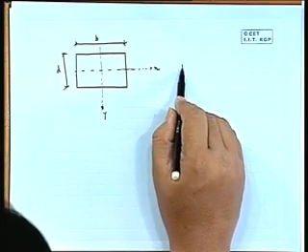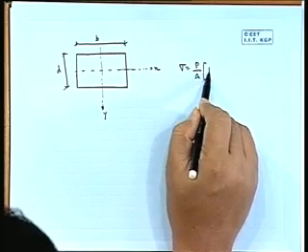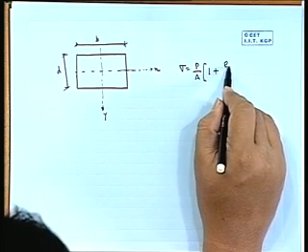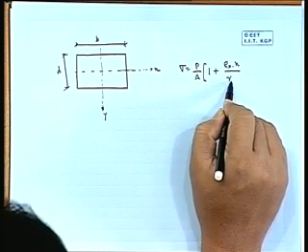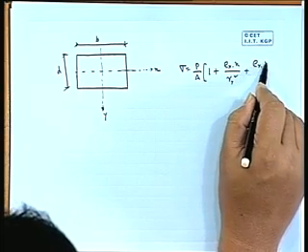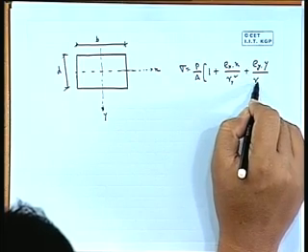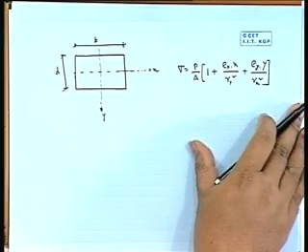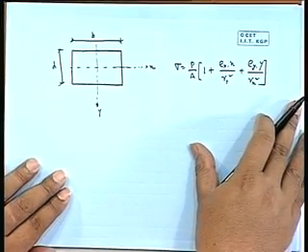Now, we repeat that expression, it is P by A times 1 plus Ex x by ry square plus Ey y by rx square, right. Say the load is acting somewhere here. So, this is your Ex, this is Ey, whatever we have defined, and stress at any point will be something like this. Now, we are interested in the limit of Ex and Ey.